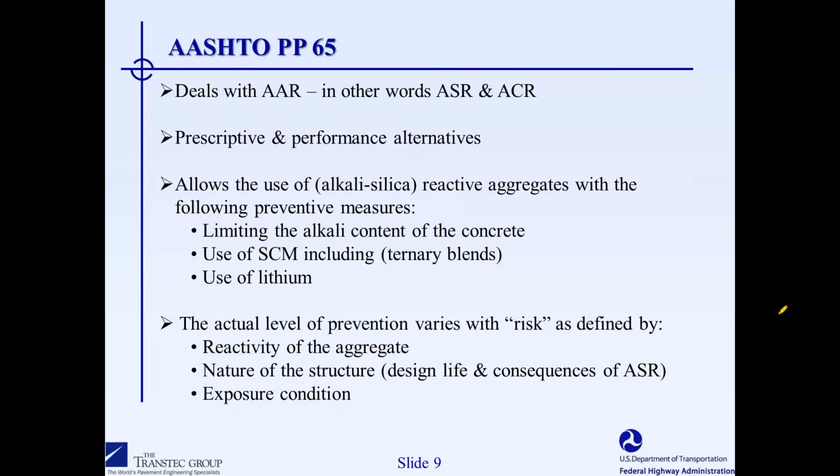One of the aspects of this documentation is that it deals with both ASR and ACR, so it covers them both. It actually gives both prescriptive and performance alternatives. It allows the use of reactive aggregates, providing one of the following preventive measures is used to limit the alkalis: using SCMs or lithium.